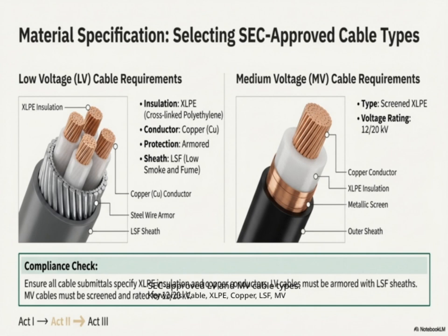Another important point is the use of copper conductors, which are preferred for their excellent electrical conductivity and reliability. When combined with insulation materials like LSF, or low smoke and flame retardant compounds, these cables become safer in case of fire, reducing smoke and toxic fumes. For medium voltage applications, these cable types are optimized to ensure efficient power transmission while maintaining safety and longevity. Overall, understanding these approved cable types helps us choose the right solutions for safe, reliable, and efficient electrical systems.